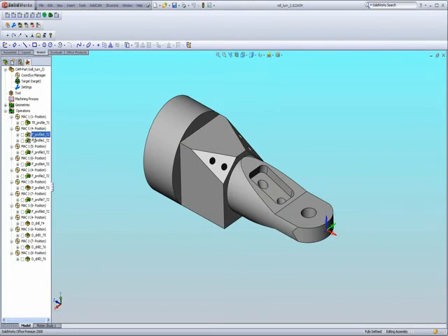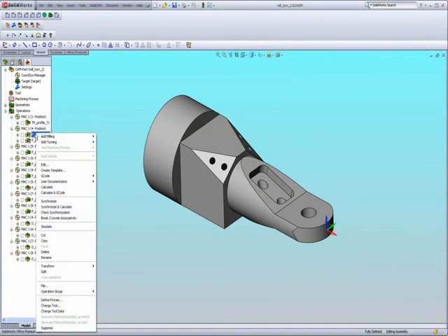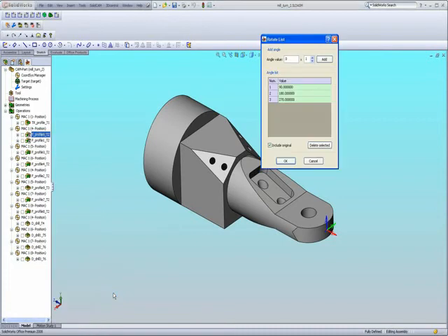But what I've done here, and if you notice there's this little 4 in this little corner over there, what I've done is actually gone into the option in my operation of transform and gone into transform 4th axis. And what I've done here is simply say the following. First, include the original.